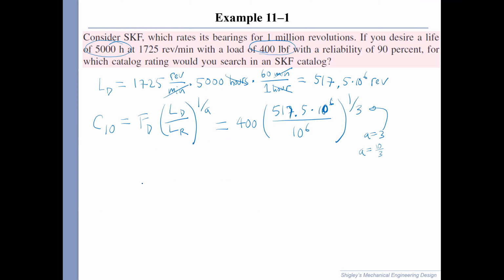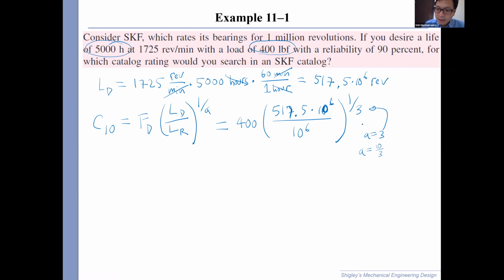Is it 10/3 or 3 here? It's 3, this is a ball bearing. It isn't stated, it's a good point. Let's assume it's a ball bearing. A equals 3 for ball. For roller bearings, we will use 10 divided by 3.